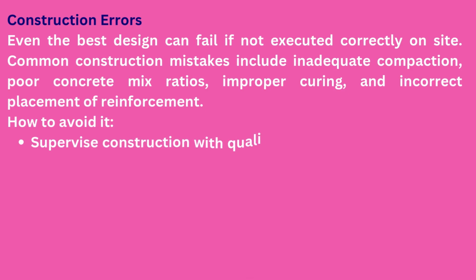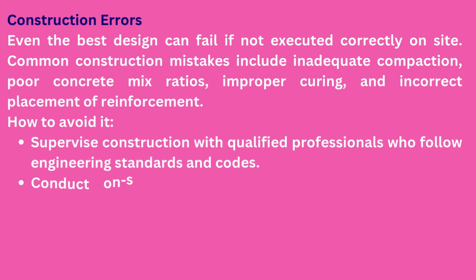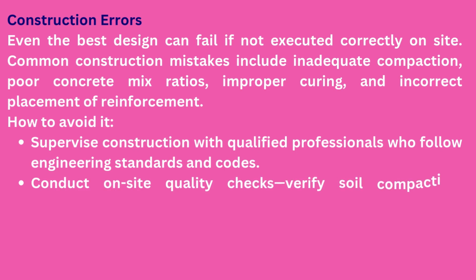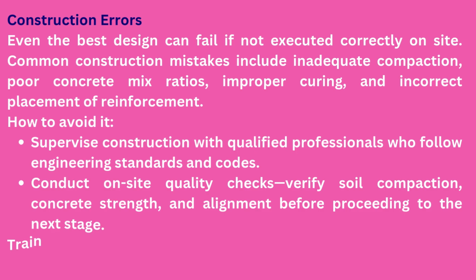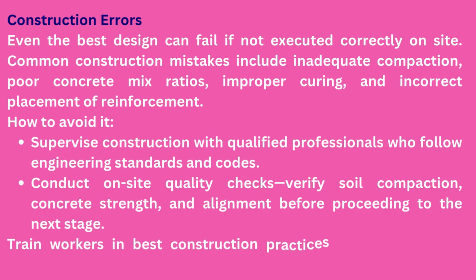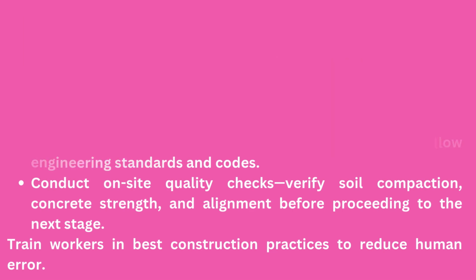How to avoid it. Supervise construction with qualified professionals who follow engineering standards and codes. Conduct on-site quality checks. Verify soil compaction, concrete strength, and alignment before proceeding to the next stage. Train workers in best construction practices to reduce human error.